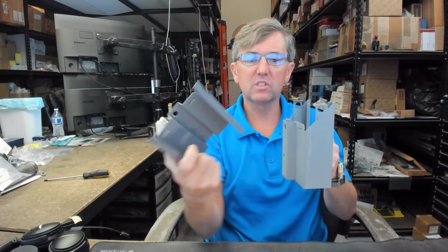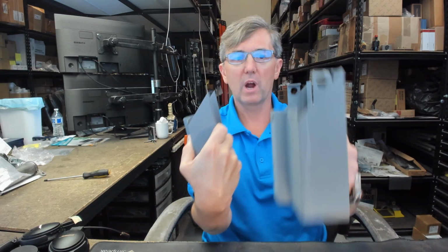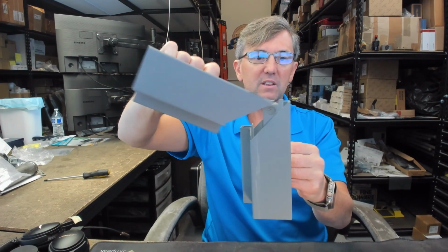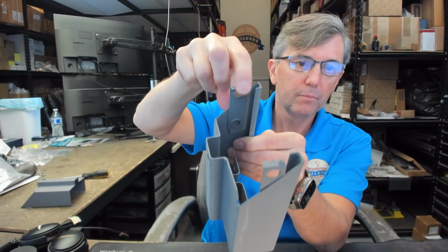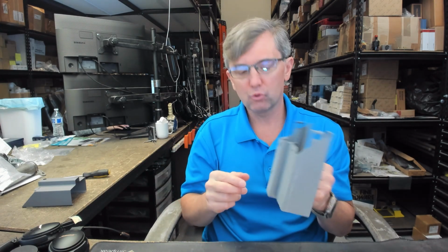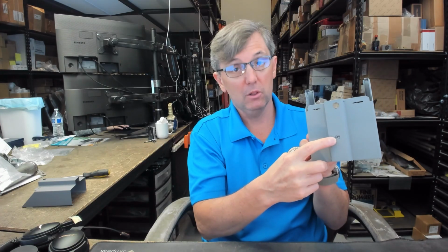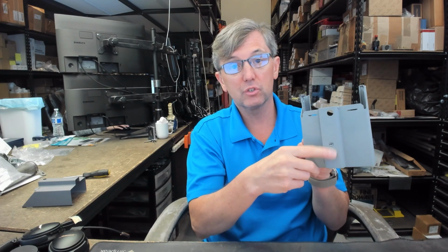You'll notice that it's different than the masonry frame. You'll notice that it's got this gizmo here. These are nothing other than alignment tabs for the miter. That's going to force the header to align nicely with the face of this. And you'll always know a knockdown drywall frame when you see something that looks just like this, a flush screw, and you see a miter.